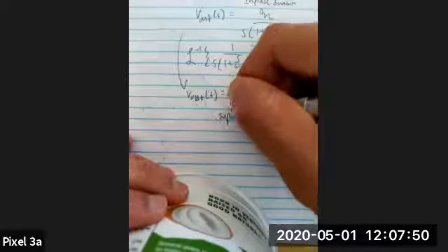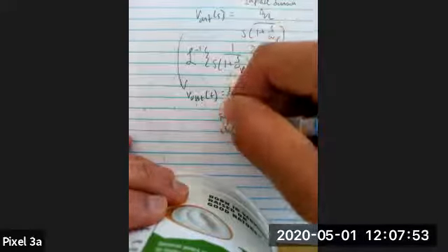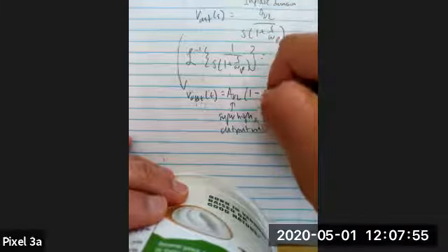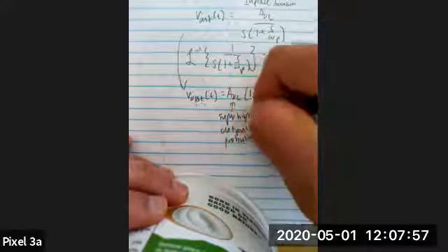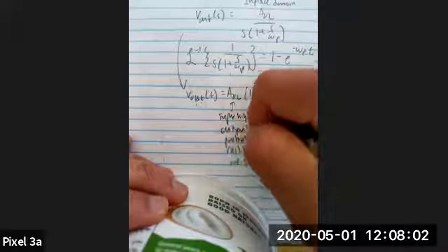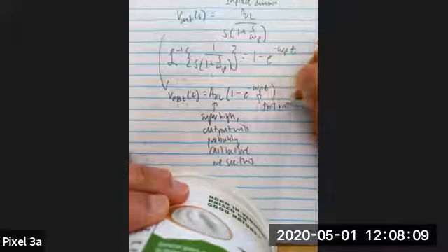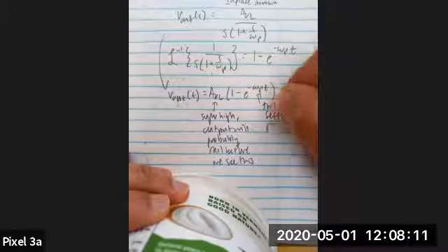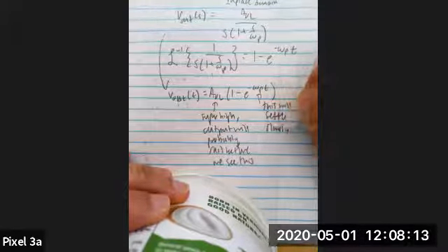And so what we see here is, I kind of mentioned this before, A open loop is super high, and so the output will probably rail before we see this. And additionally, omega p is really slow, and so this will settle slowly as well, which is not good on either count.